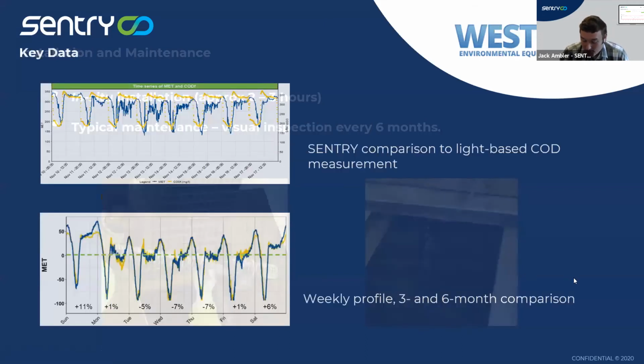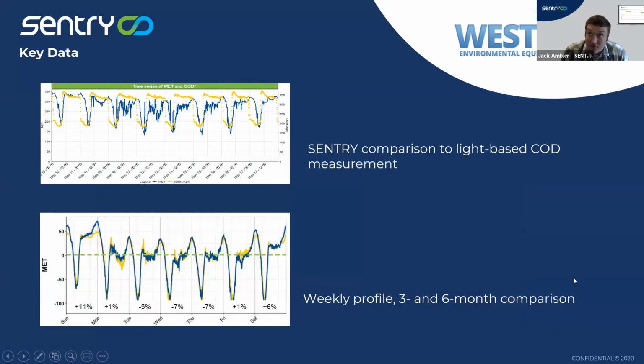So yeah, I think there's a lot of really important stuff in the collection system. However, it's very difficult to get in there. It's difficult to get systems in there. It's the worst type of wastewater in the industry, besides some industrial ones. So your equipment needs to be very low in maintenance, and it's very often difficult to get in to even do anything. You might have to shut down a road. You might be entering a hazardous area. So low maintenance is crucial to keep reliable data going here.